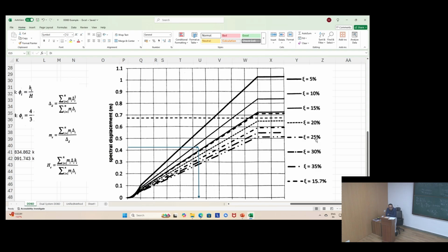Your theta YF changes, but nothing else changes, right? So you'll probably be looking at a different line on the displacement spectra for your TE. Your forces will change. So let's see what you find out in terms of your TE for the short direction and your forces. Just the total base shear should be fine.